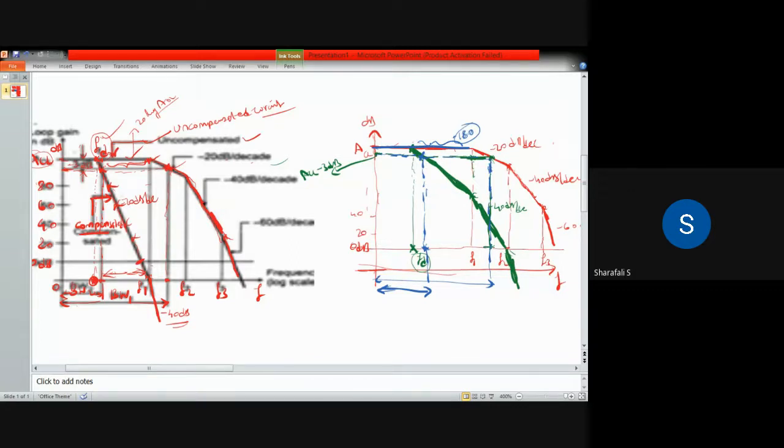That will be less than that of F1, F2, or other higher break frequencies, and your gain will start decreasing from this point. So in this condition, you will be having A beta which is less than 1, even though you will be having minus 180. So by that means we can make our circuit stable. Okay, so that is the function of this compensation network.